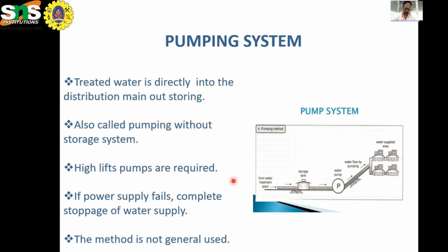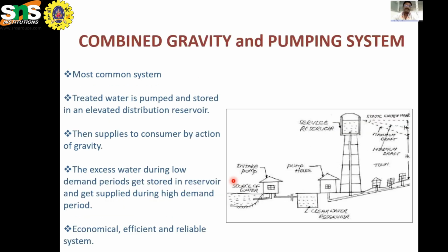It is also called the pumping without storage system. High lift pumps are used. If the power supply fails, there is complete stoppage of water supply, so the method is not generally used. Nowadays we are not going for this method. It is obsolete.